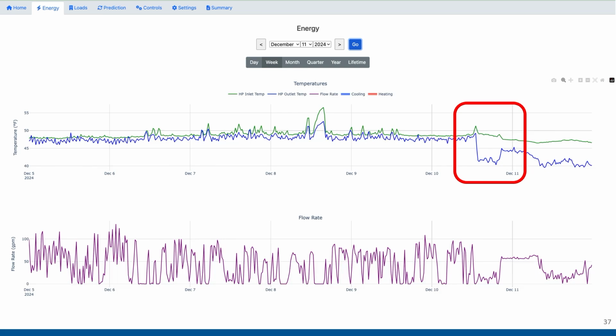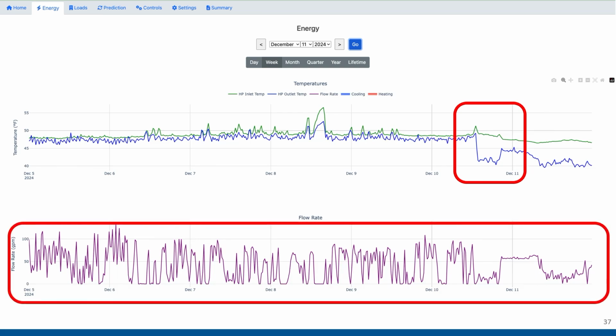And again, those VRF units have two modes, right? Water and glycol. When they switched the units to glycol mode, they were able to allow for entering water temperatures of 27 degrees Fahrenheit, which is for a geothermal application. They were able to lower that set point of the backup electric boiler to around the 28, 27 degree Fahrenheit mark. And then you saw this big decrease because the ground heat exchanger was actually allowed to do its job. It also fixed the cycling on the flow rate side because the pumps were allowed to operate more evenly. But again, only the person paying the energy bill probably would have caught this.